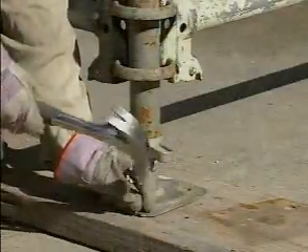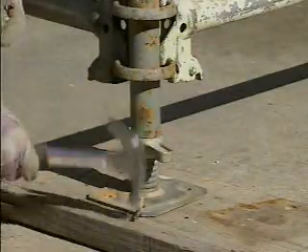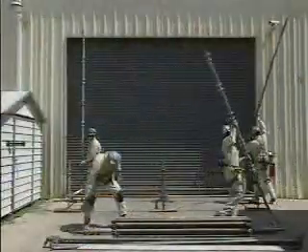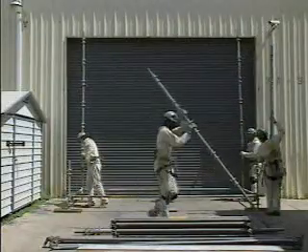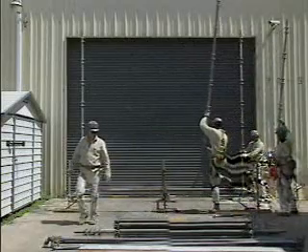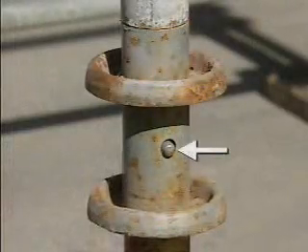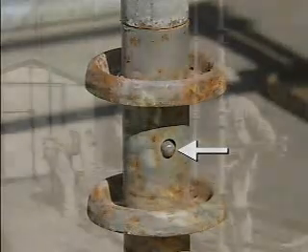Then they nail down the base plates of the screw jacks to the sills to secure them. With the lower framework in place, the builders next install vertical legs over the coupling pins in top of the starter collars. The coupling pins have spring-loaded pins that lock the vertical legs and the starter collars together.